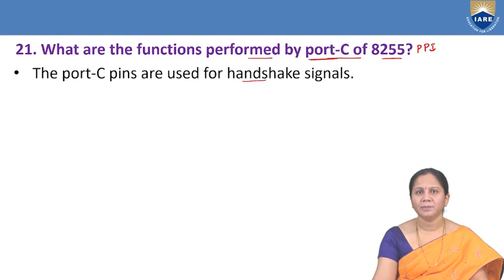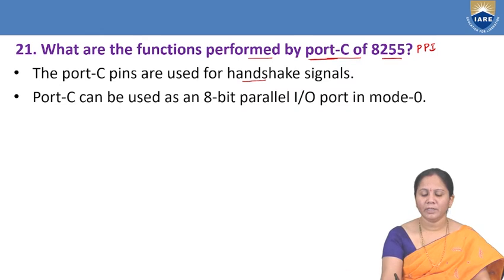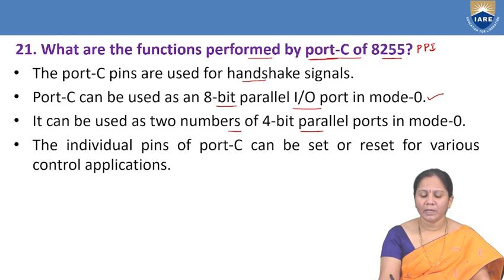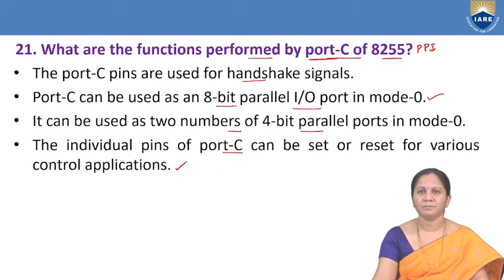And port C is used as an 8-bit parallel I/O port in mode 0, and it can be used as two 4-bit parallel ports in mode 0, and the individual pins of port C can be set or reset for various control applications.